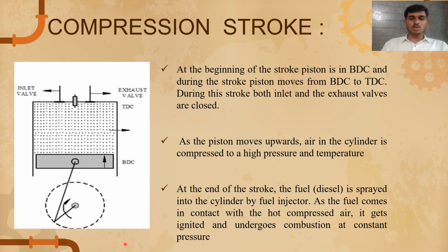At the end of the stroke, the fuel, which is diesel, is sprayed into the cylinder by the fuel injector. So this is the fuel injector, and the fuel comes in contact with the hot and compressed air. It gets ignited and undergoes combustion at constant pressure.